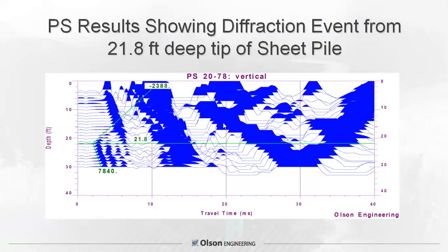So the data from this was kind of unusual, or probably what we should have expected. We really didn't get much signal directly from the sheet pile or the concrete wall directly through the soil, through the levee material, because it's such loose fill and it's not saturated. But when we got down to the firmer materials, down to the pile tip, we got what I think of as a classic inversion here. And we have almost what we call an arrow pointing at the foundation tip.